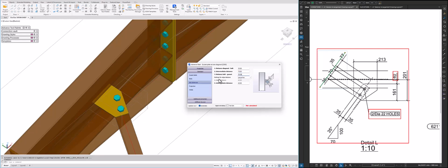So now we're setting the bolt distance from the edge of the angle iron. So according to this drawing of ours, that means our bolting is set to the center line of the leg of the angle iron. So instead of gauge line, you click the drop down arrow there and then say center line. So the center line, as you can see now, it says edge distance 35,